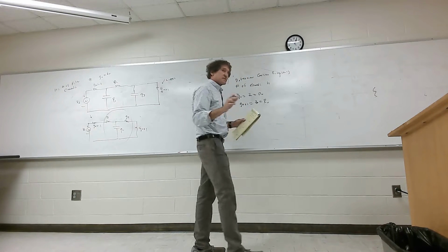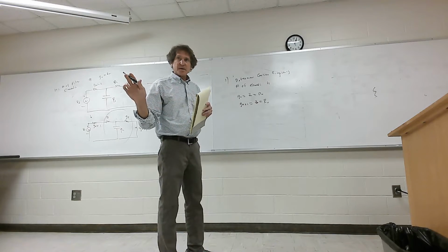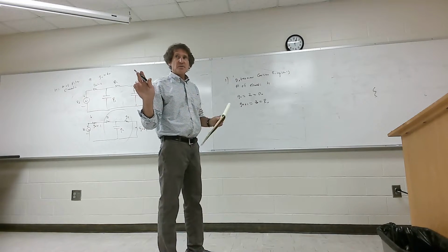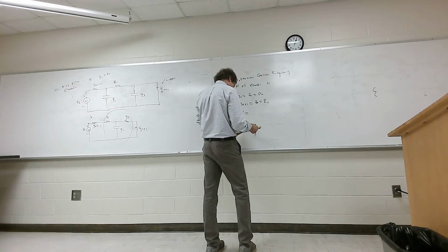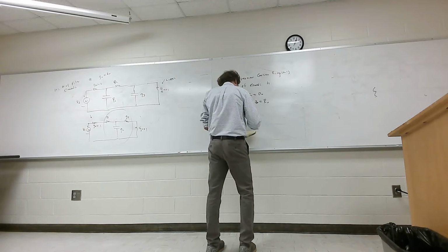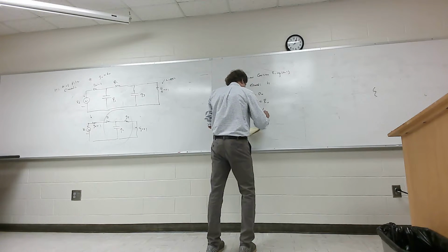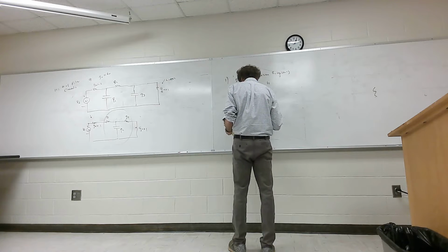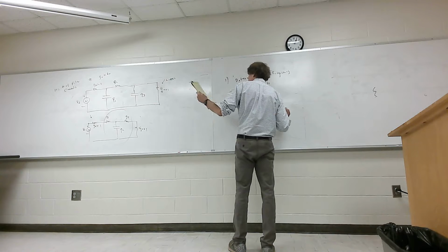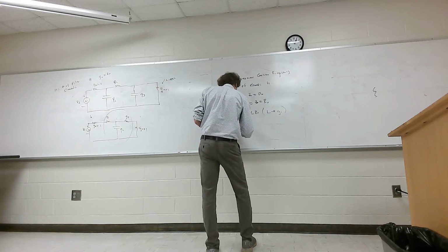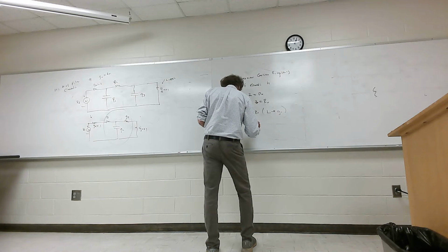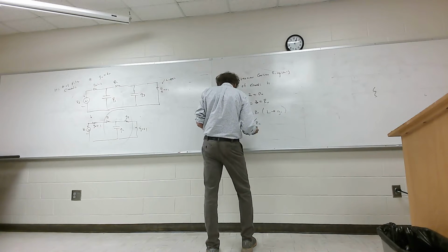Now this is an intermediate stage, it's not the final stage. We're going to find these values that will be used for the next step. You're going to get something called L prime, which is equal to L times R naught. Here, I'll explain this in a second. L comes from these G values over there, which is G1, and I'll get to that. And you'll get C prime equals C over R naught.